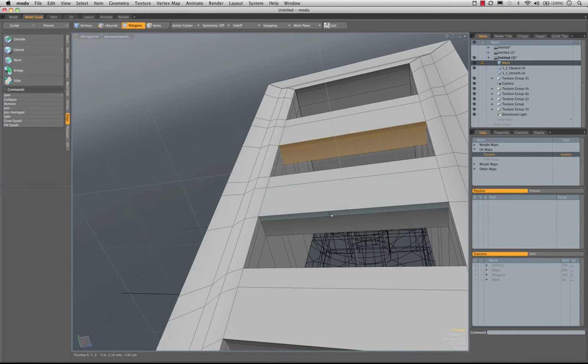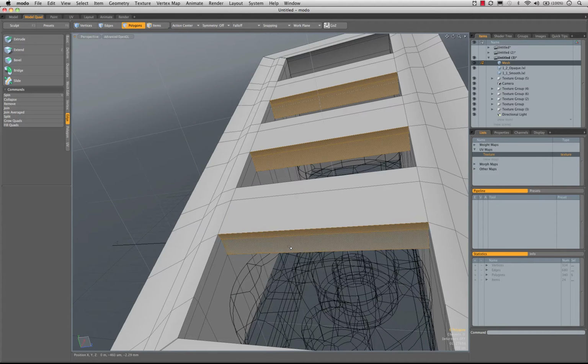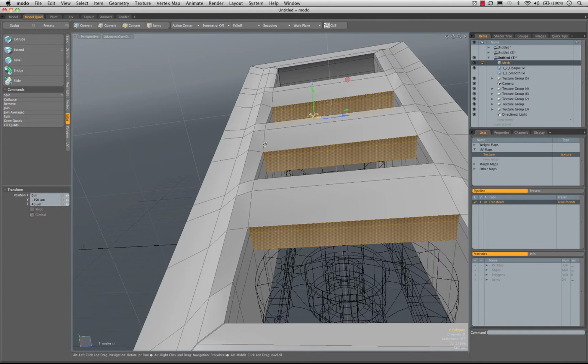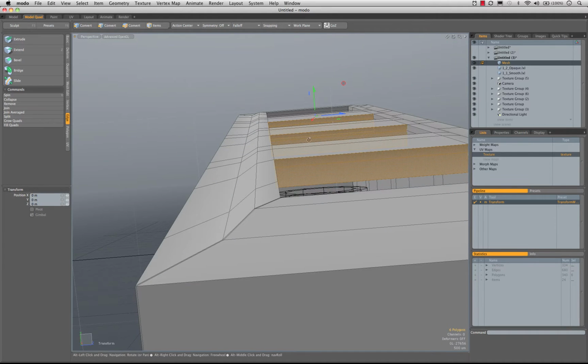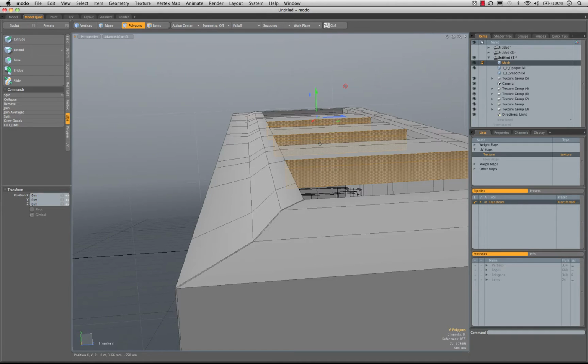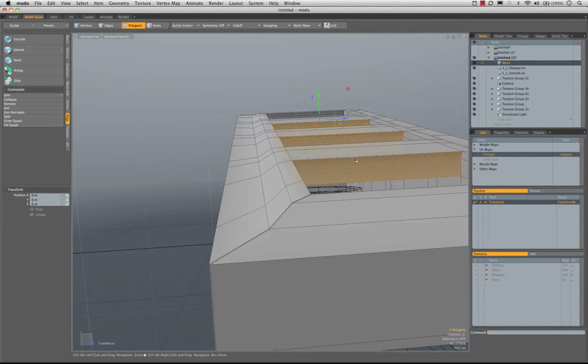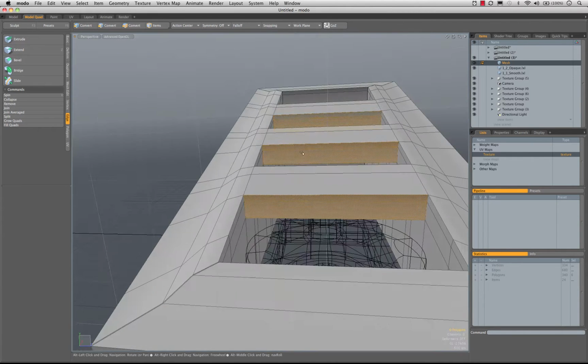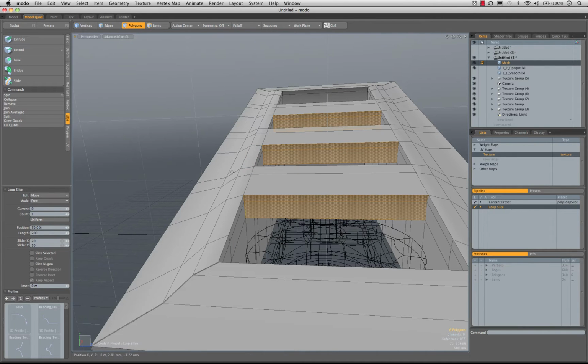But if I just grab this geometry right here and I pull this down, it's going to cause some definite weirdness. You can see this is now going to be dipping up and down the whole way down. And actually, if you look really closely at the plastic, there is a little bit of distortion that happens where this tapers. But the other thing that you notice is that there is a loop that runs a little inner ridge down here. So we're going to take advantage of that, and our subdivision surfaces will take up that small detail that's in there.